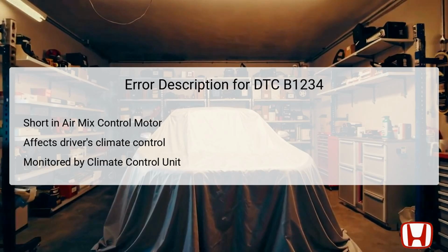An automatic recorded drop in this voltage indicates to the unit that an abnormal condition has arisen. This malfunction can lead to an inadequate climate response, compromising comfort within the vehicle. The component must be tested relative to other associated parts to confirm whether it's the primary culprit or a consequence of another failure elsewhere in the circuit.